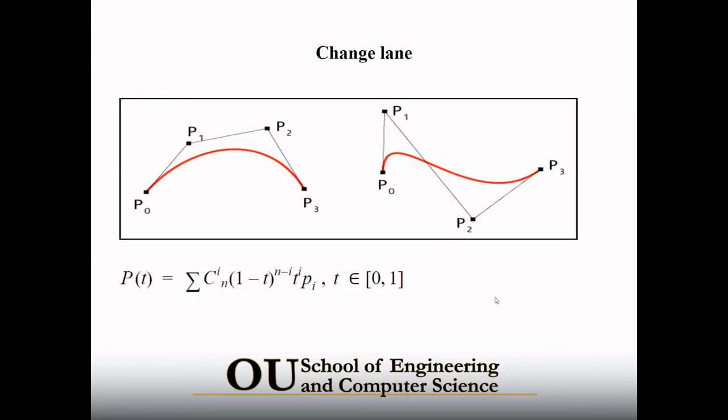So now for lane changing. Lane changing is very important for the IGVC because for some courses we are required to change lane when there is something like a construction barrel in front of the car. In order to change lane smoothly, we need to generate a path that the car will follow smoothly. And we chose to use Bezier curve equations in order to generate